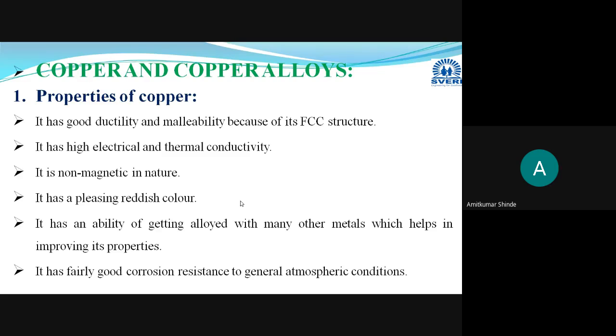properties of the copper. Now there are some general properties of the copper. You are already aware of this, because you have already studied copper in school. I will repeat it: copper has very good ductility and malleability, and these properties are there in the copper because of its FCC crystal structure, face centered cubic crystal structure. Copper has FCC crystal structure.